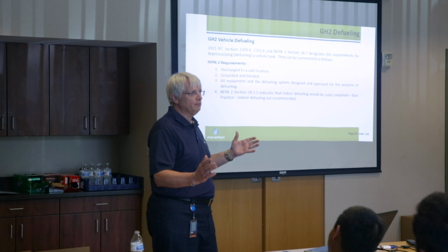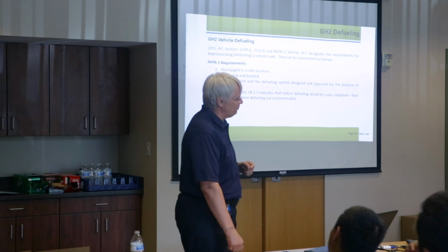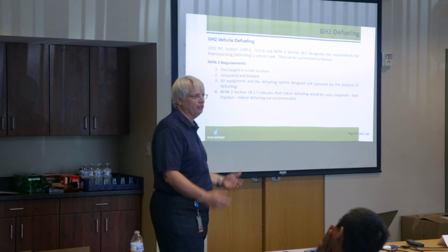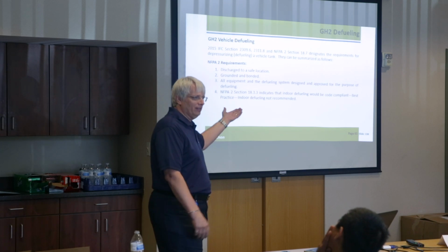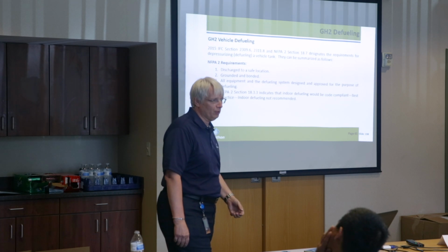It shocked me. But no, it is surprising, and there have been situations with static discharge where you can actually ignite the gas, and then you have a torch. So that's why everything has to be grounded and bonded.